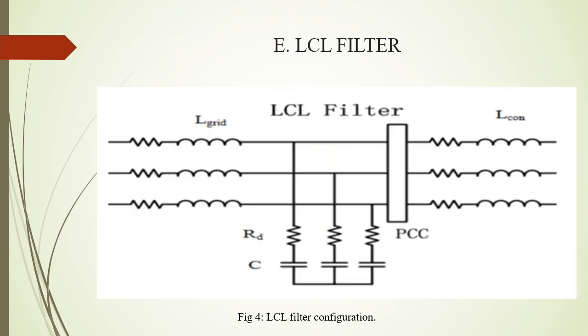This is the LCL filter. This LCL filter is a passive filter implemented to reduce the harmonics, which cause disturbance in the line current and low voltage, resulting in poor power quality and an impact on the system.